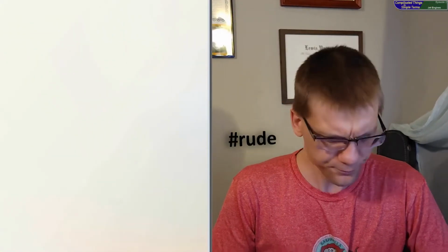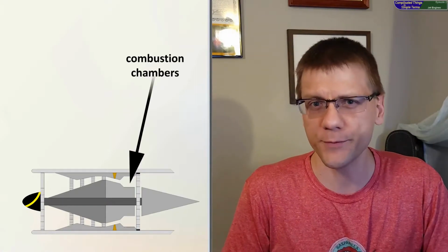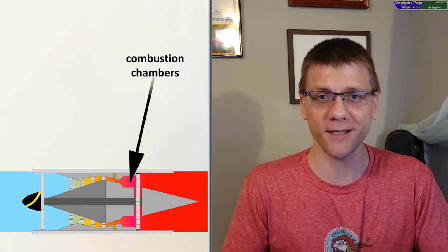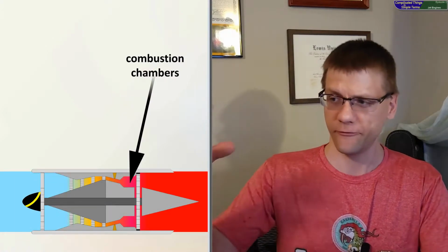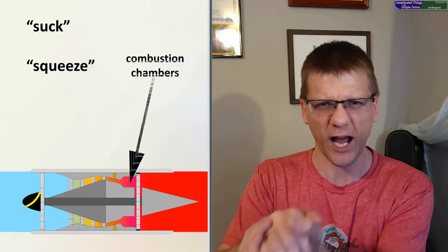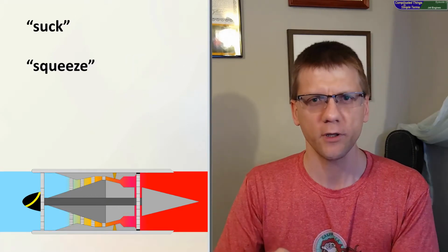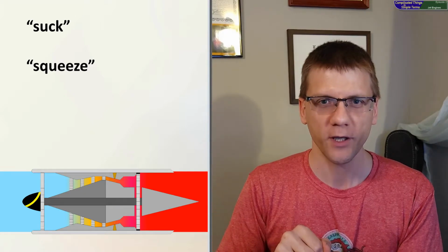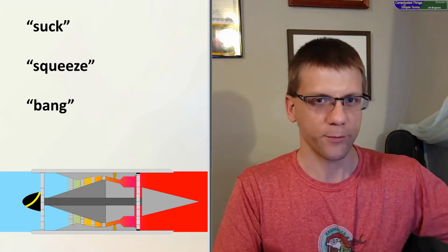unless someone comes along and blows it out. The same exact thing is true of a jet engine. There's no timing, there's no spark plug that has to fire at just the right second. There are igniters, and those get the whole thing started in the first place, but once it's going, it keeps going. So, fan at the front sucks air in, series of smaller fans compress the air into a hot, dense, small volume. We then spray jet fuel in, and then we ignite it, and it explodes out the back.